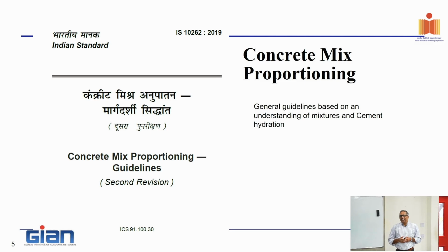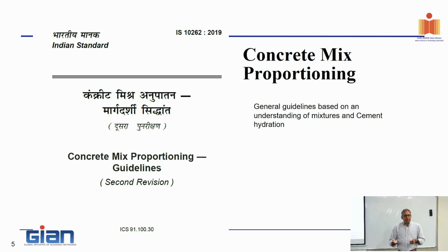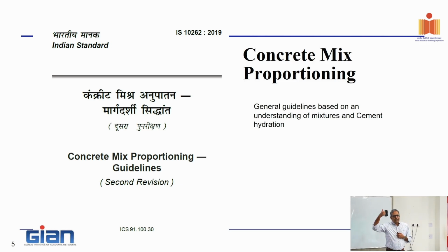Okay, except they're stated in layman's language because they don't expect a practicing engineer to understand the concepts of packing or rheology. So they're framed in such a way that thou shalt do this, right? And in doing so, they hope that some basics are covered. And what are our objectives in doing the concrete mix design? Strength and durability, workability or flow, and economy.